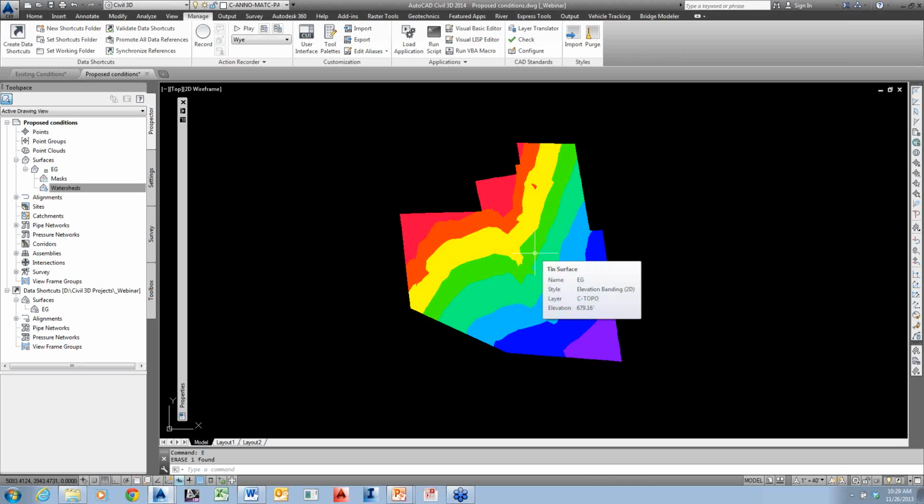We're asked, how about adding boundaries to the reference surface? I believe that changes the data, so can this be done? That's a really good question. Can I add a boundary to this surface? No, I can't. I can't add a boundary to it because, as you mentioned, it actually changes the data of the surface. However, I can add a mask.